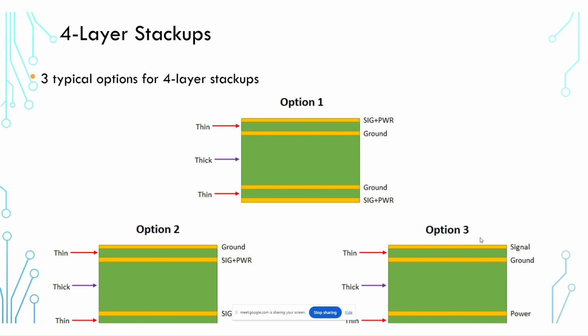So if you can keep your analog stuff in one region on the top side, and then your digital stuff on one region on the top side, you can then actually make routing a bit easier for yourself in terms of power by having this internal layer dedicated for power. And in addition, with this power layer, it doesn't have to be one plane at one voltage. You could actually split this up into multiple rails, and those multiple rails could have different voltages.